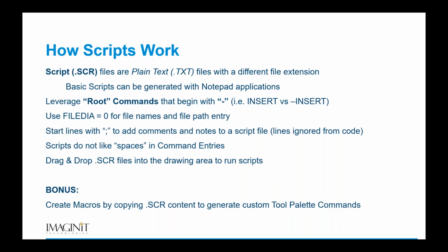How do you get the escape key to stop a command? You just have to press escape. There's no key in command for escape. The Control-C, Control-C thing that works with macros does not, unfortunately, work with scripts. So if you are at the end of a command, you just have to press escape on your own. And if you get all the way through your script and the last step is just, the prompt is there and you need to cancel it out, I would just be hitting escape anyway.